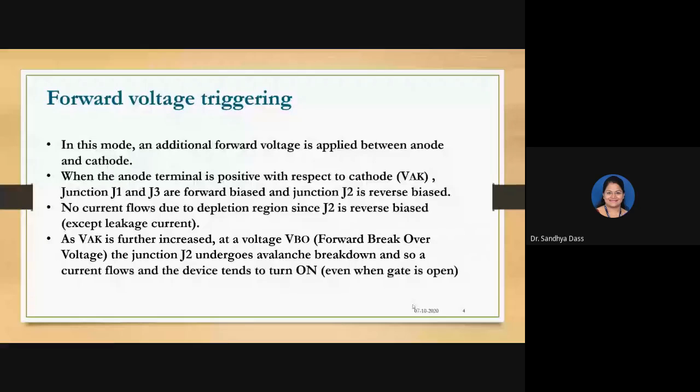For a diode, a simple PN junction, it is 0.7 for silicon type, and 0.3 for germanium type. For an SCR, you need to remember the voltage across it when turned on will typically be around 1 to 1.5 volts.